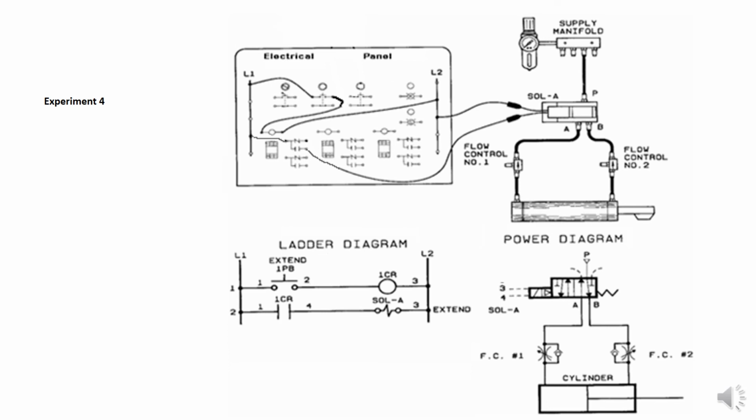The circuit for experiment 4 appears on page 164. It makes use of a device called a control relay. A control relay is an electromechanical form of switch with contacts. They form logic functions, and often they can be used to open and close circuits that conduct a little bit more current than the controlling circuit.